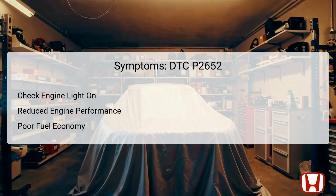This malfunction can adversely affect the vehicle's acceleration response, resulting in sluggish performance. Additionally, a drop in fuel economy may be observed, as improperly functioning VTEC engagement can lead to inefficient engine operation. Pay close attention to these symptoms, as they will guide you towards identifying the presence of DTC P2652.